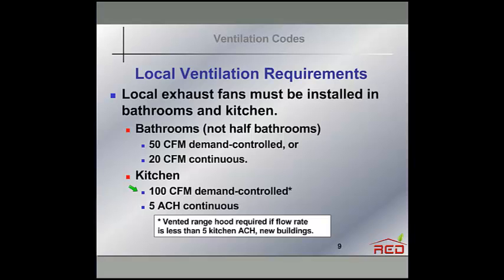So various fans have different capture efficiencies. Various speeds in the fans will change that. Over my kitchen range, I have a microwave fan combination. That fan is vented to the outside, but it's merely a box over the range. It has a fairly low capture efficiency. And by the way, a recirculating range hood counts for nothing. It must be vented to the outdoors.